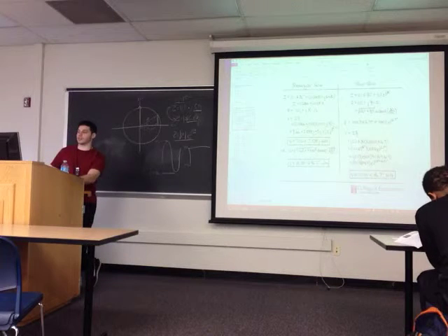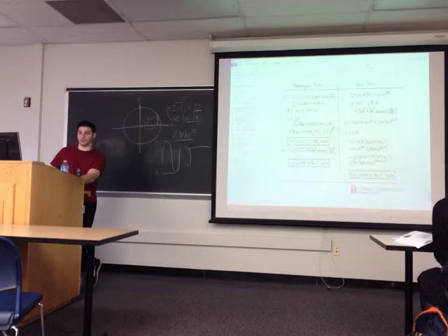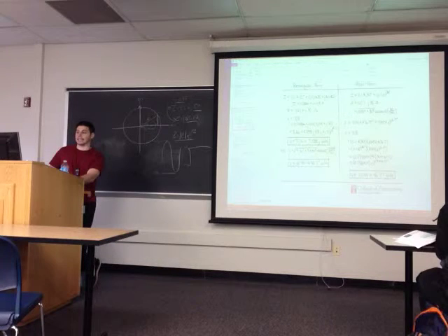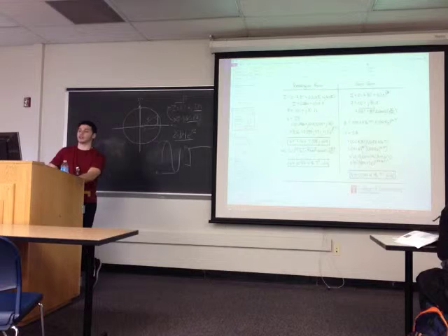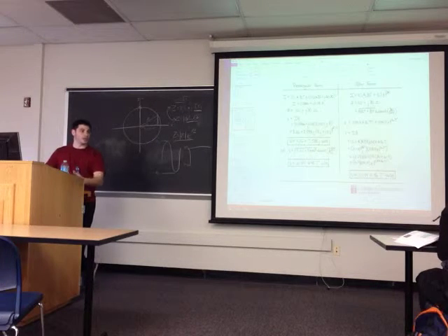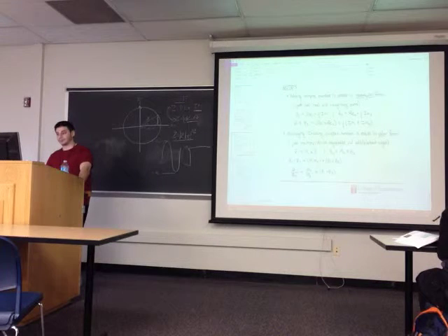You can see that there are fewer steps here than right here, doing it in rectangular form and multiplying, because we have to distribute the two quantities and then collect all our terms. You're more likely to make a mistake doing this than just multiplying your magnitudes and adding your angles. So multiplying is easier in polar form, and addition or subtraction is easier in rectangular form.